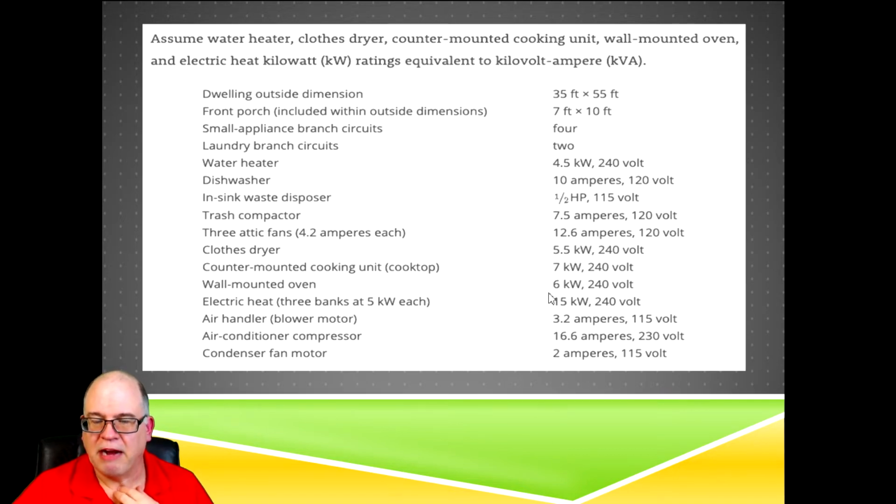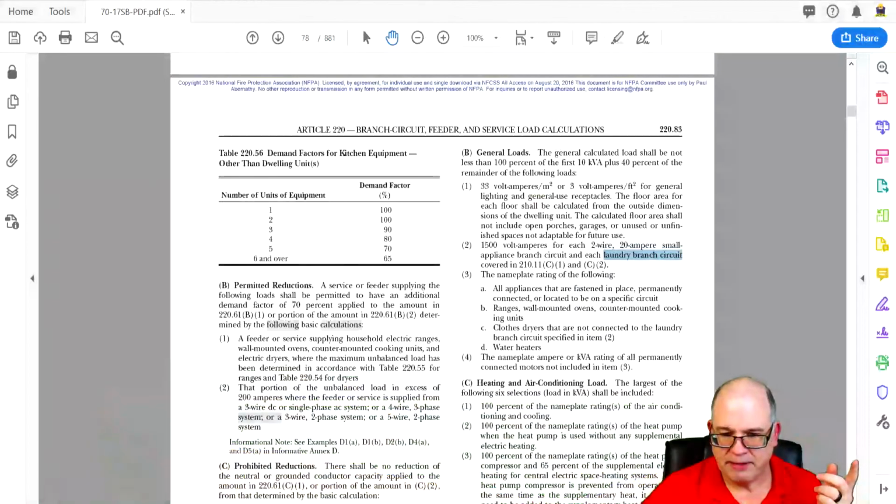All right. Now, ironically enough, the water heater is an appliance, but if we look at the NEC, under these options here, you'll see that the water heater is by itself under D, and we're including it kind of as an appliance. But just so you understand, the water heater is also included in there, and you're taking the actual nameplate that you're going to get from that, okay? Still might have to do some math, but you're getting that math from the nameplate, okay? I just wanted to make it clear as we move through with this.